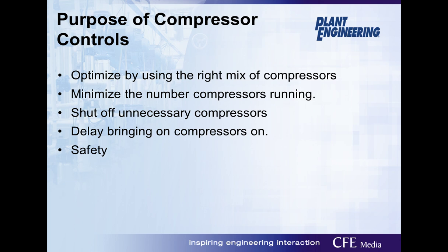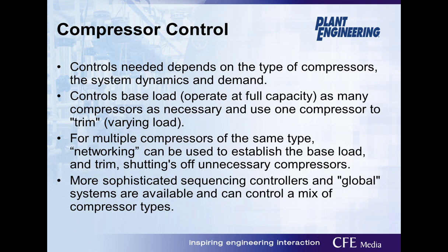So the controls of a compressor play an important role in doing all of these pieces, making sure that you have the right compressors running, the ones that are better at base load, and the ones that are used for trim that have better part load efficiency. And you want to go through and minimize those numbers. And that's really what we want to look at when we look at compressor controls a little more in depth.